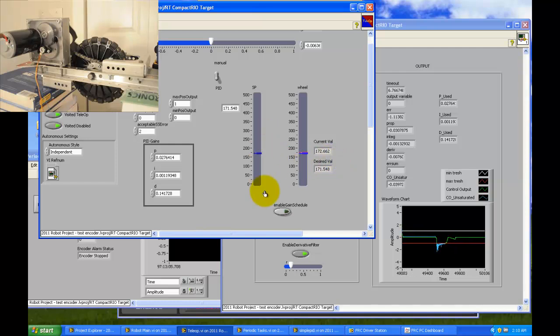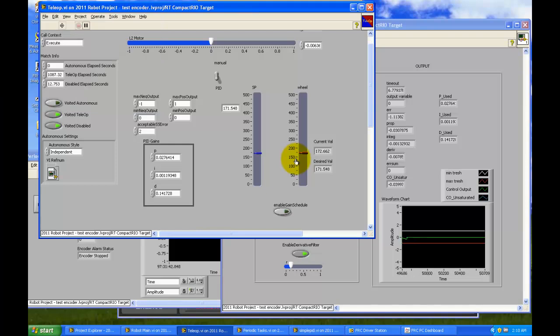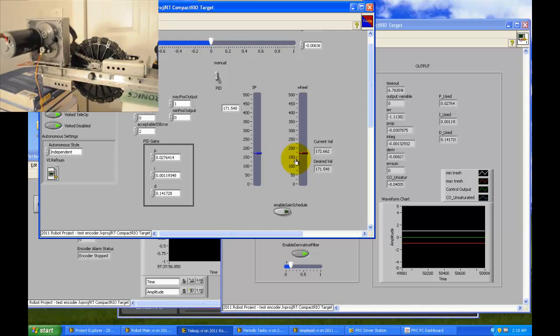Now, if I were overshooting, I would try and make it less aggressive. One of the other things that you got to make sure is when you're doing this that your controller is in brake. And I'll show you, I'm going to switch my motor controller to coast mode, and I'll just show you how completely different the response is. Okay, so my controller is now in coast mode, and it was in brake before, so now I'm just going to drive it forward.